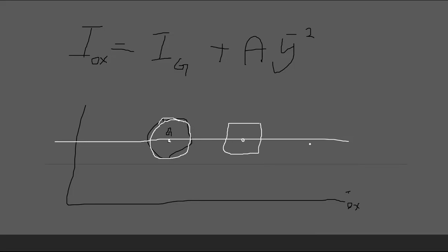Then this y bar is the distance between the centroid axis and the axis you need to find I about. A is the total area, nothing different. If it is somewhere far away from the axis you need, you have some additional term.